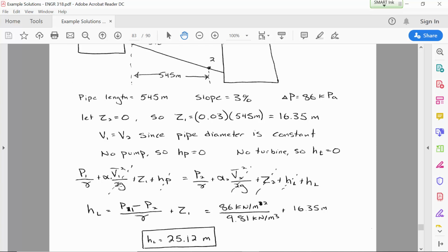So we know that because the pressure change should have been other than what we measured. If there was no losses due to pipe friction, then the pressure at location 2 would be greater. But since it's less, we attribute the difference between the two to be because of the losses. Any questions about those calculations?